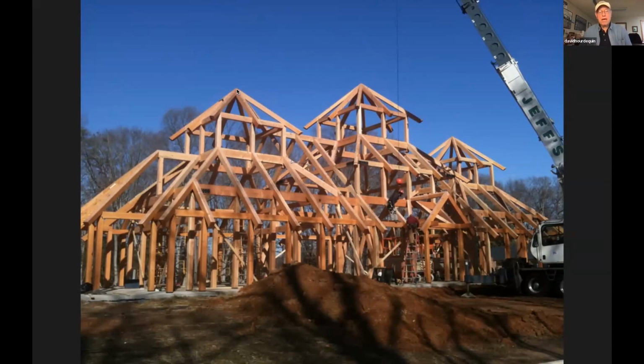And the way that you do that, I just divide up the forces, summarized into 4 components. I don't worry about this rafter, it's going along for the ride. It's the ones at the hips that define the tension ring. And so when you put all the design loads in, this has a certain compression in it that gets transferred into this corner, and it's trying to shove the corner in a direction parallel and collinear with the hip.